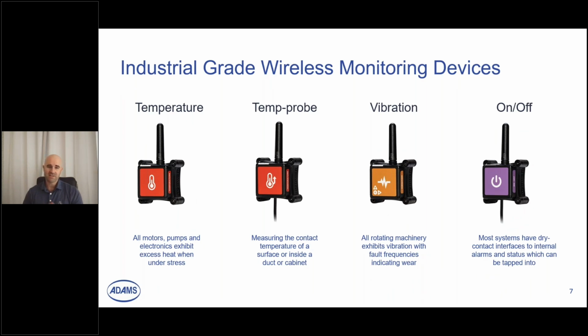So some of the most common sensors here on the far left, we have the ambient temperature sensor. I've put these in a lot of different server rooms at manufacturing facilities. Obviously, as the electronics fail in a server room, they're going to exhibit excess heat. That is an ambient temperature sensor. So this is going in an industrial bracket like this here. You can slap that in here, it magnetically attaches. This has double-sided tape backing, so I would peel this off, stick it on a wall, and that's going to give you inside of a panel or inside of a room the ambient temperature of that environment.